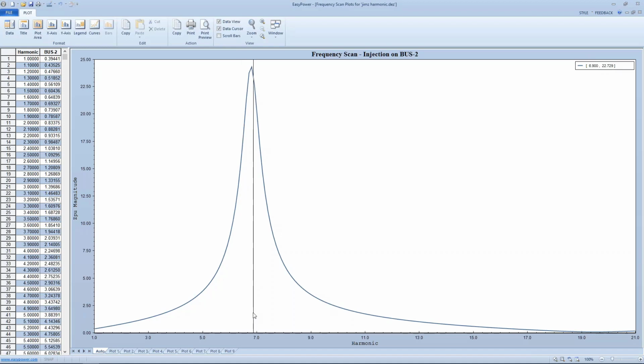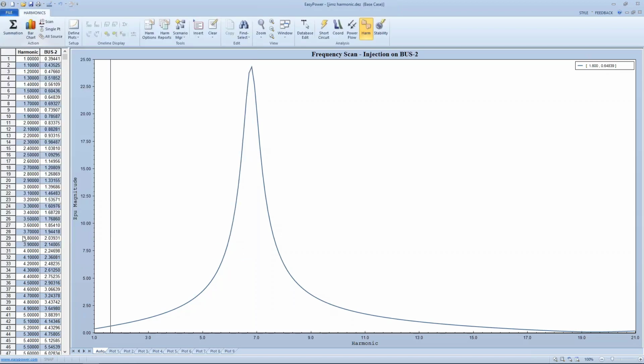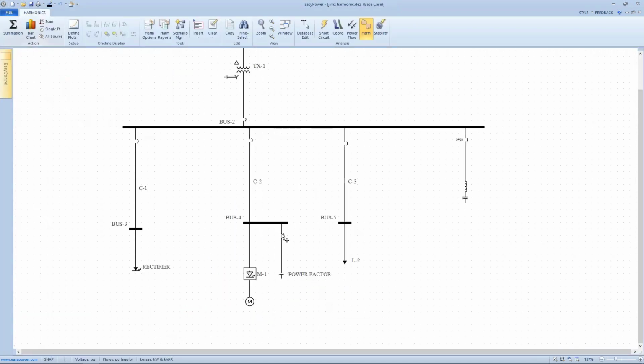So back in the day when power factor was the vogue and I threw this on my system, it may not have caused problems if I didn't have any harmonics floating around in the distribution system. And that's why the problem arises. Now if we put VFDs in the system, do they generate any frequencies that coincide with that particular resonance?